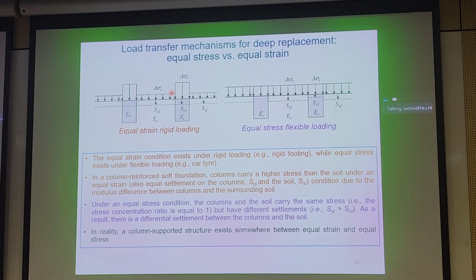We probably have to consider the tensile strength of these columns. We're probably worried about, okay, so soil we're quite familiar with when we carry out Plaxis, but what kind of material model should we use for these composite columns, right? Does it behave like concrete? Is it very flexible? These are perhaps some of the issues that we need to cater for. And these are some of the problems we're facing now.